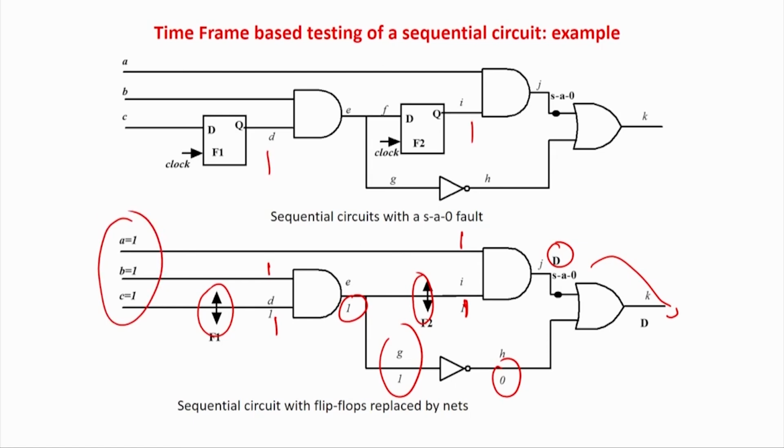Now you see this is done, the ATPG is done. So if this is a scan flip flop, or non-scan flip flop, this ATPG has to be done. So now what it says is that the output of the flip flop has to be a 1 and this has to be a 1. So if it's a scan chain, what will we do? We will do nothing. There is a scan business, so you can directly set them to 1 1. So your ATPG is done.